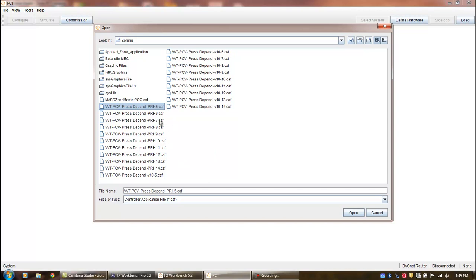Each group of 10 have pre-addressed MAC addresses and pre-addressed device IDs. There are also independent peer-to-peer communication settings for each MAC address. MAC address 5 will be communicating with zone 1, MAC address 6 for zone 2, 7 for zone 3, down to 14 for zone 10.